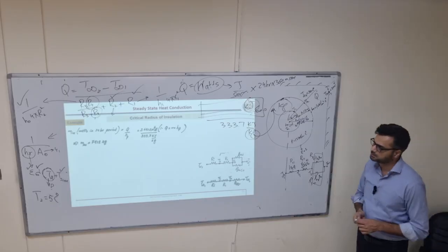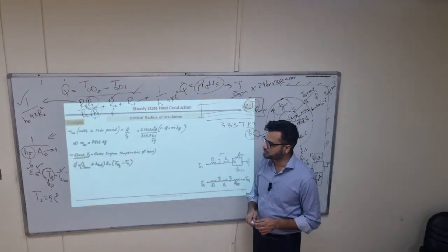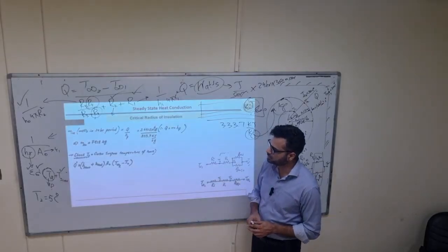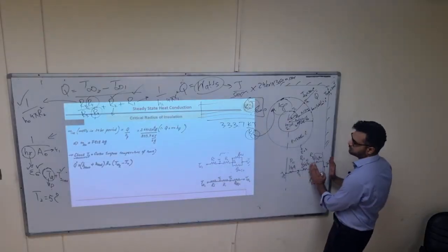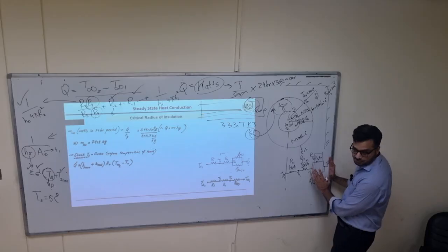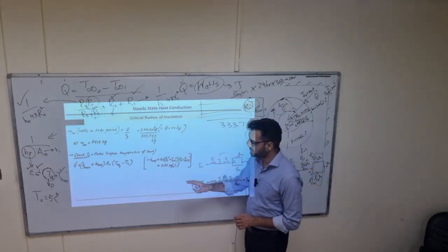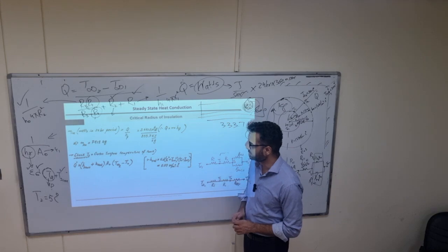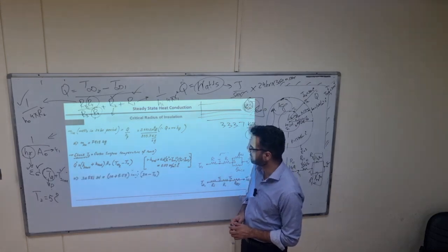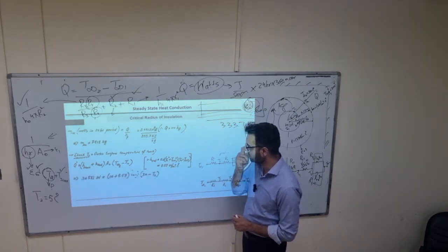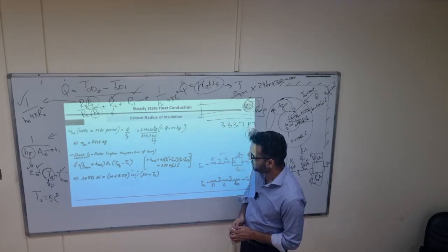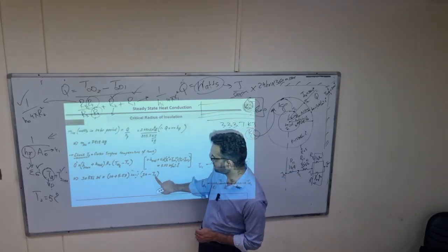Thick insulation. Okay, to check whether T2 was correct or not, we are using that Q dot for this part, from T2 and T infinity 2 for this part. So here H radiative, which you already calculated, in H radiative, T2 is actually unknown.